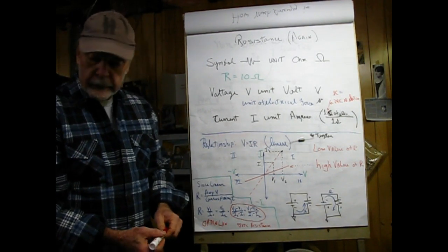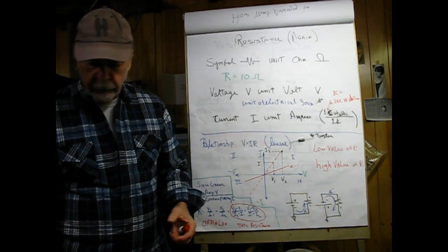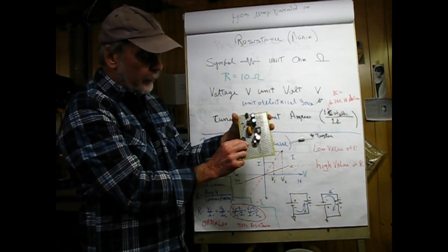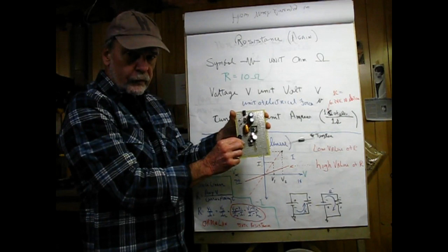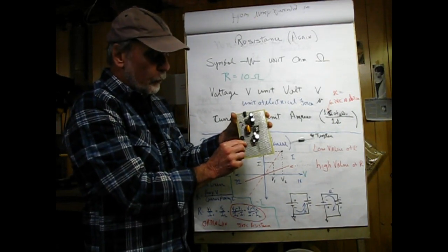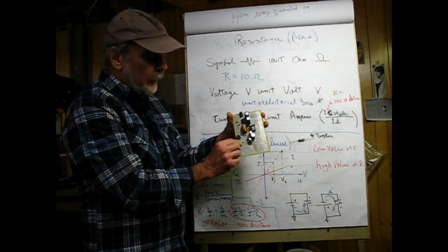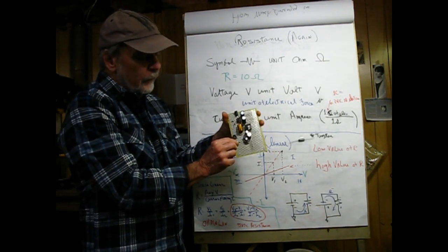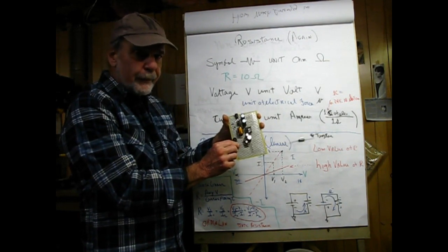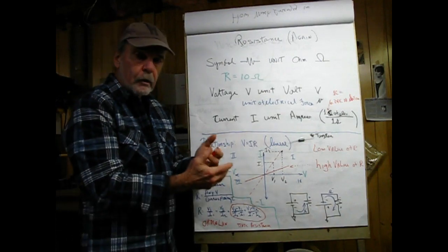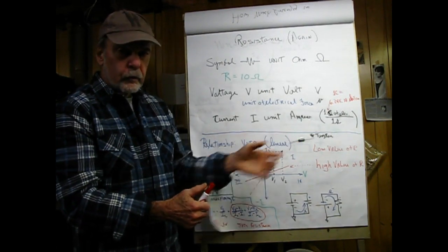If we're using a surface mount part, I don't even know if you can see this, the corresponding resistor would be the same package size, which is called 1206, and would be about that large. And why would I need a resistor, which in this case is 1/8 of a watt? We'll see that an LED is nonlinear and something has to limit the current. So there's a need for a physical component that resists current flow.